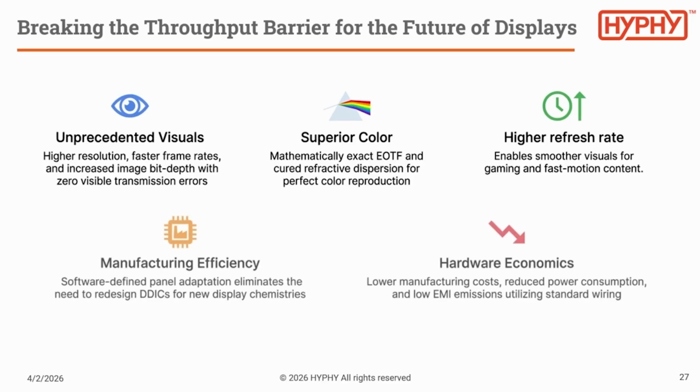And, well, maybe unnecessary to show, we can do much, much higher refresh rates than digital transfer. I haven't discussed that, but manufacturing efficiency is also increased because it basically eliminates all needs to change display driver ICs or D2A converters from display panel to display panel. And hardware economics is better because we don't need any EMI shielding, which is also a problem with current digital display drivers. So with that, I'd like to conclude.